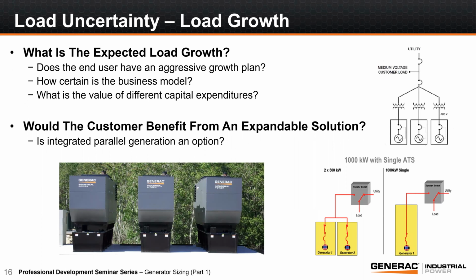Historically, this is done by installing a larger generator if they think that they're going to expand their operations in the near future. They would have previously just added a large generator with the anticipation of how much they think they will be adding in the future. But this can cause some negative results like poor use of initial capital and possibly wet stacking, because the generator is too large for the load that is currently on it. And you don't want to do that because it could cause more issues, and you may end up having to replace that when you go to extend your operations.